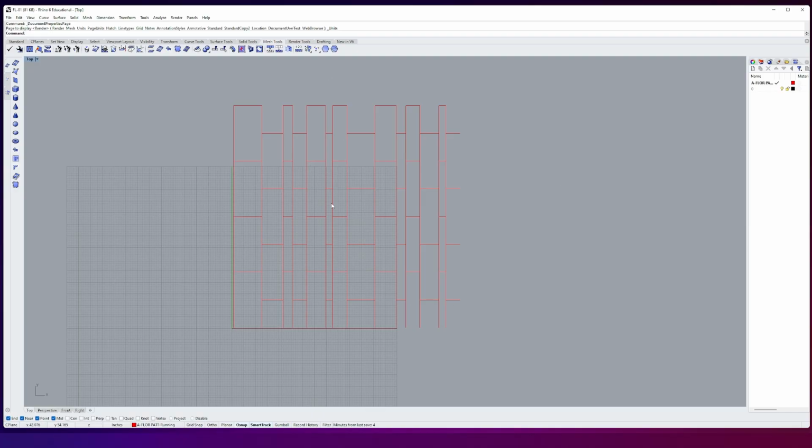And you can see here I've created a pattern already, and you can see that it's a perfect square and that some edges of the pattern don't have a line closing them and some edges do. And that's important because when we tile this pattern, we don't want these lines to duplicate and overlap with each other, or else you'll get overlapping lines, and when you print off your CAD drawing, you'll see an extra dark line for where those lines overlap.